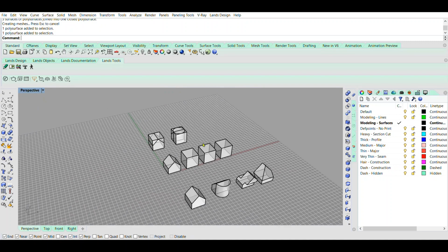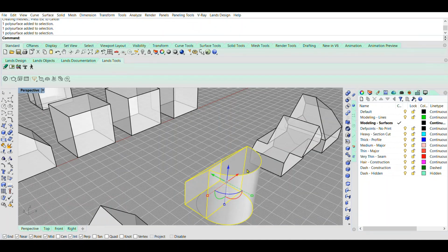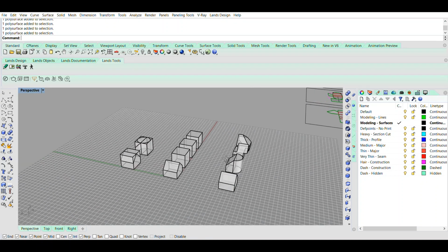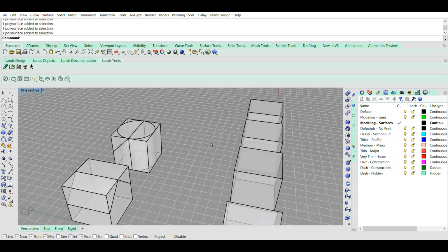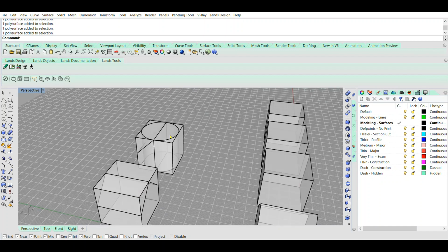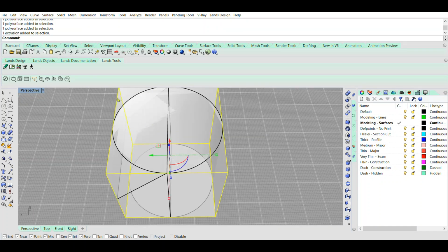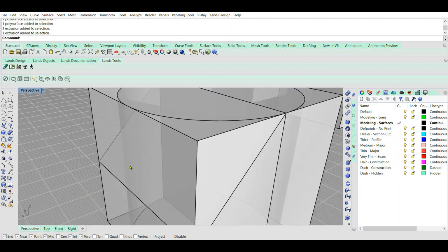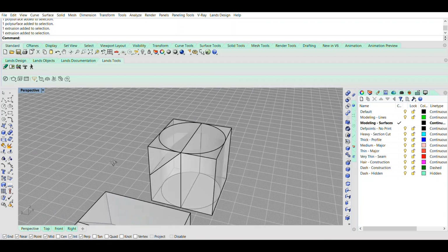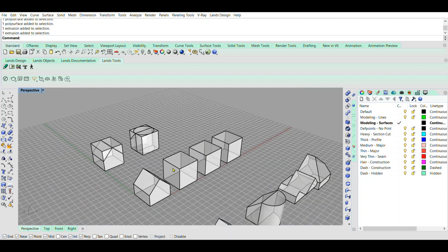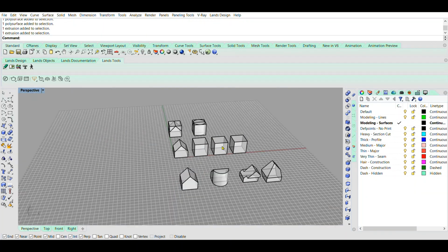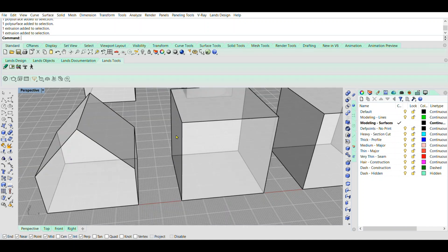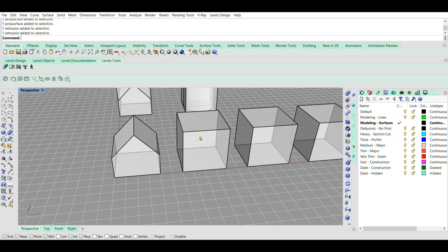And then next we're going to model this half cylinder, half box slanted shape really quickly. You'll see there are multiple steps to this one. First we'll model a cylinder, then draw some more of those planar surfaces, and trim again to do that. And then for these, in the next video, the modules will talk about the Boolean objects.